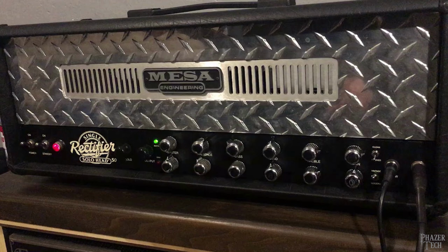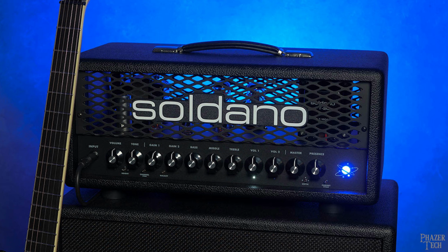For example, many high-end guitar amplifiers contain multiple channels, and relays are a common method used to switch between channels. But it's also common to see other methods being used, including transistors. So this is an application where both relays and transistors are acceptable, and it comes down to personal preferences and the trade-offs between both devices.